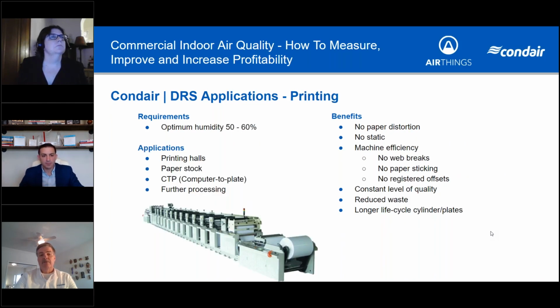Printing, very similar. Obviously, you see a little higher humidity level. Again, I'd like to just touch on some of the benefits here, because for the commercial side, we want to focus on how we're going to help you improve your operations, reduce downtime, improve your quality. And here on the printing side, the humidity is needed to maintain the integrity of the material that's running through the machines. As soon as that material gets even slightly out of spec, you can run into issues with the machine going down, poor quality, and a lot of waste and scrap and rework that needs to be done.